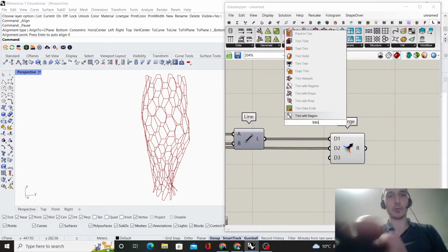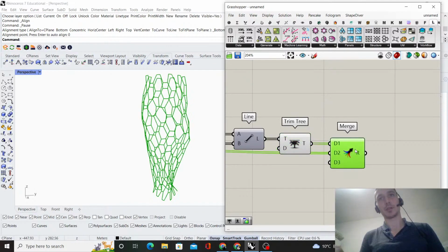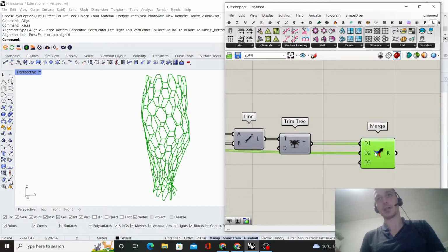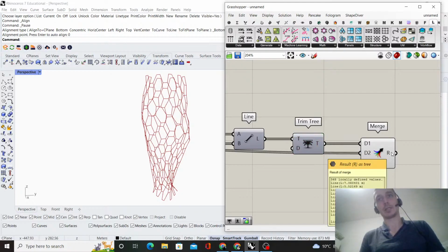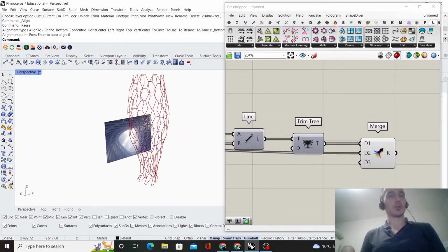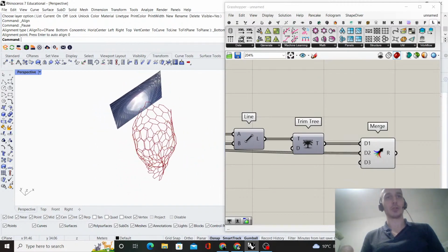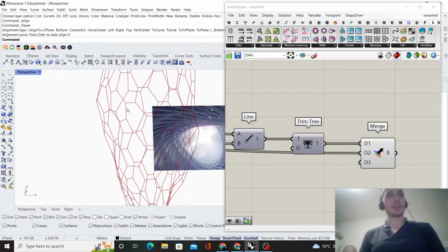So in order to change this, I'm gonna trim 3 here, because you see we connect two very similar data structures together, but as a result we get a data tree with its paths having different lengths, which is quite bad every time. So you should try to make your data structure as clean and correct as possible. So right now it's basically merged into one tree branch. Okay, so in one list if you want.